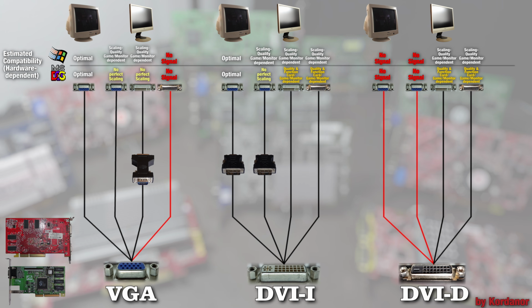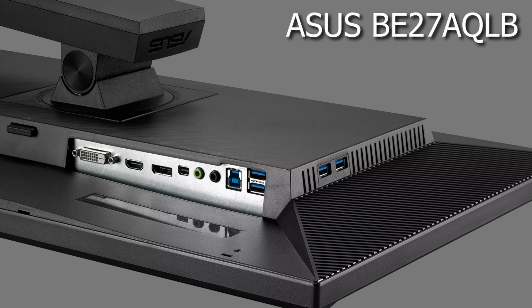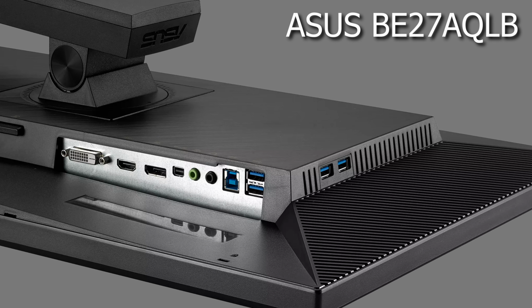And the same is true for a VGA connector going into a DVI port of a monitor, as long as it supports an analog signal. However, if you have a monitor which only accepts digital signals, then also a graphics card with digital DVI is necessary, and adapters won't be of any help.